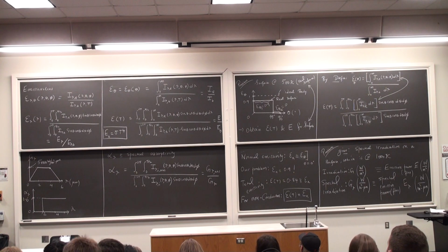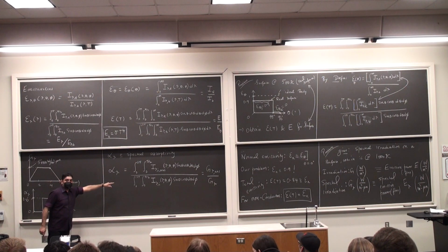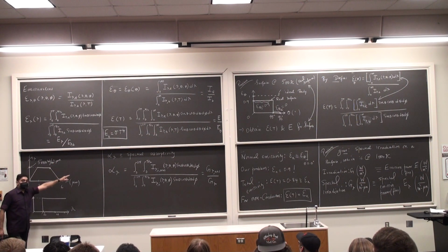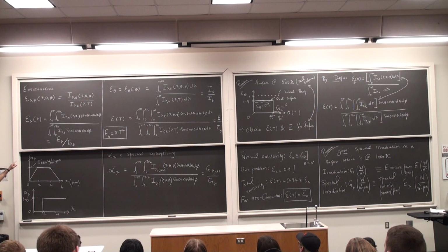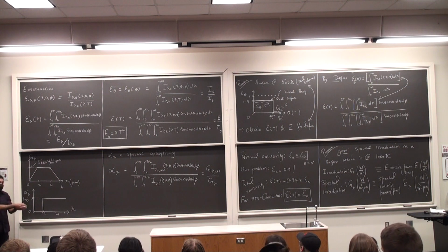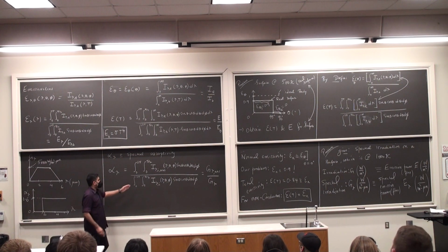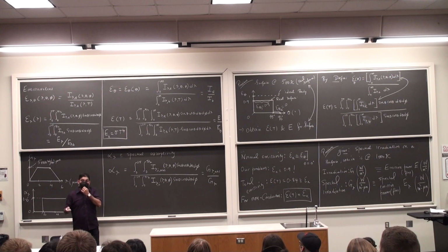Look at the similarities. Okay, so right on the top panel there you have epsilon lambda. Right down here you have alpha lambda. They are very similar looking creatures. The only difference being, in the denominator for epsilon, I am always comparing the emissivity of any real surface to that of an ideal surface. I don't have that right to do it for absorptivity because I am not sure if the surrounding surface that is sending me energy is an ideal surface or not.